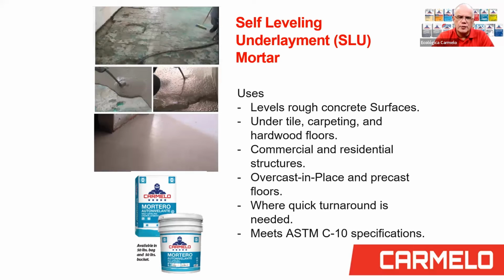You would level out the floor first and smoothen out that surface so that you have a nice level floor before you put your tiles, vinyl, carpeting, or epoxy. And again, you would be doing that about 24 hours after placing the underlayment.